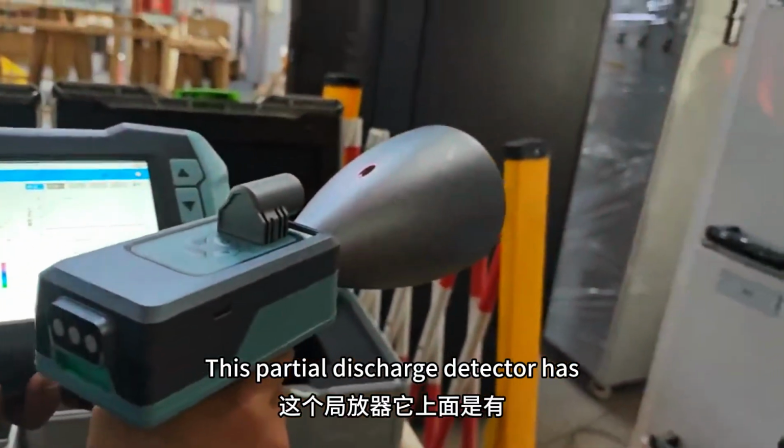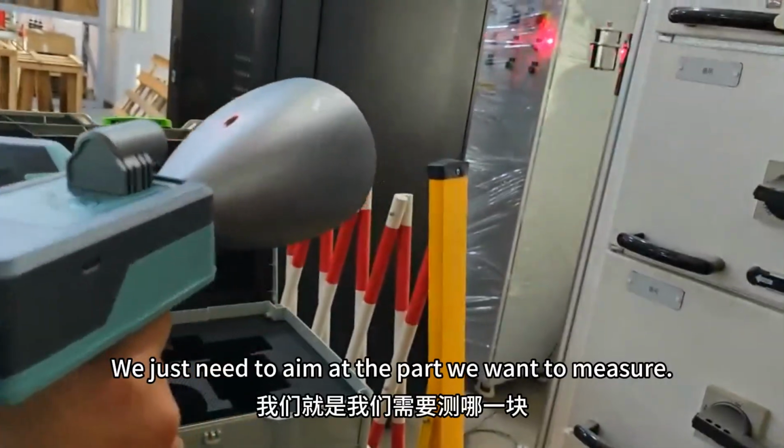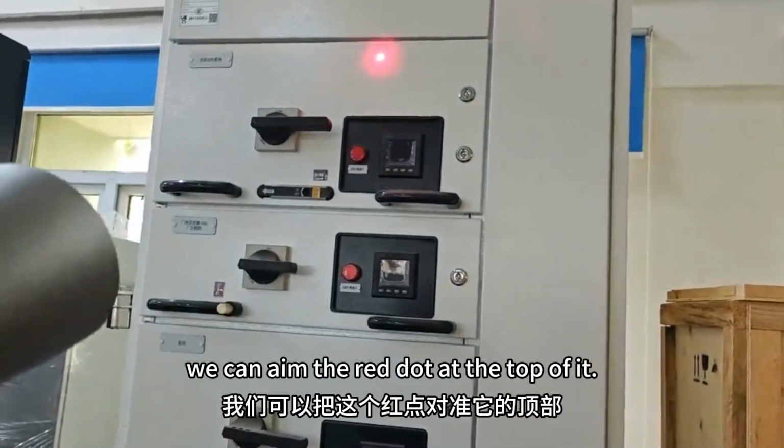detector. This partial discharge detector has an infrared laser aiming. We just need to aim at the part we want to measure. Then we can align a red dot with that. For example, if we want to test the top of the distribution box, we can aim the red dot at the top of that.